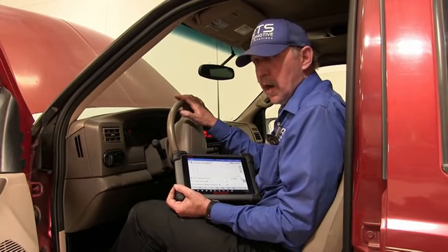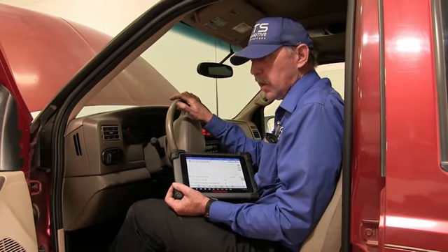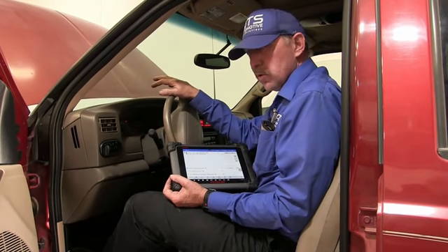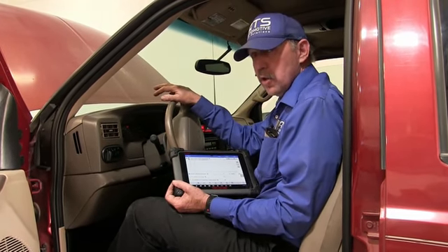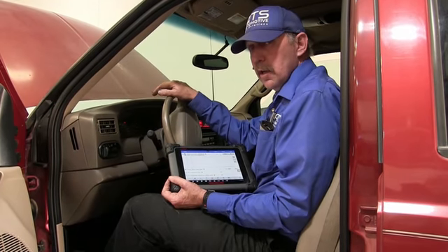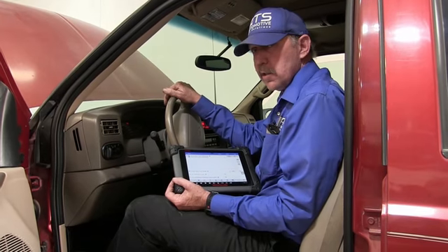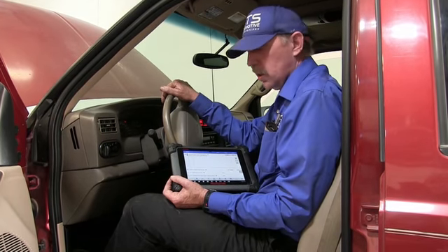That's why I was hired, is to figure out why the car is stalling. The coil and the plug fixed the stalling issue. Now what I need to worry about is to make sure that we don't get this car back. So let's go ahead and put some fuel cleaner in the tank and go drive this and see if we can't clean these injectors easily.